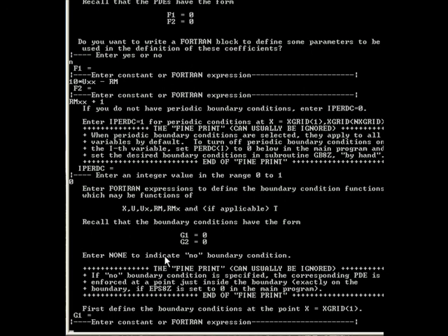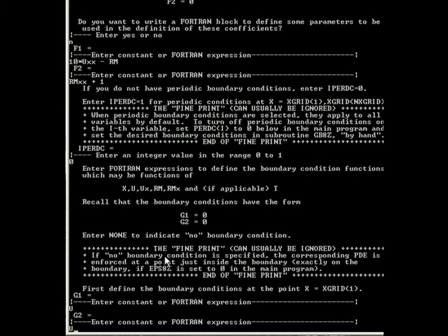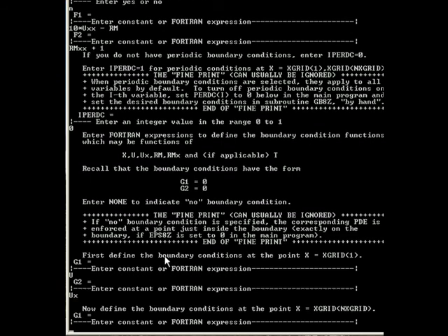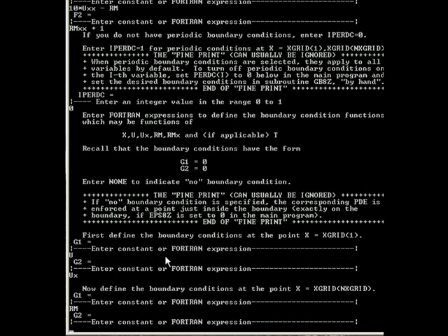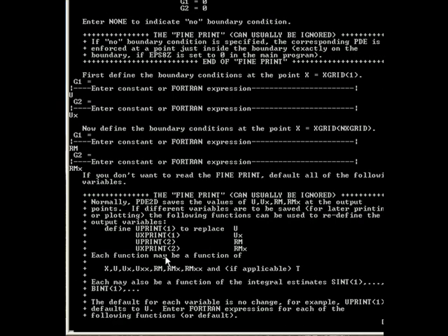Do we have periodic boundary conditions? No. Okay, the boundary conditions: remember at the left-hand point, it was clamped, so U and UX were 0. The right-hand point was free and unsupported, which means the second and third derivatives of U are 0, but you can't write that, because the boundary conditions can't involve second or higher derivatives. They have to be first derivatives or lower, but remember that was just M and MX. If the second derivative of U is 0, M is 0, and third derivative 0 makes M sub x 0. So there's our 4 boundary conditions.